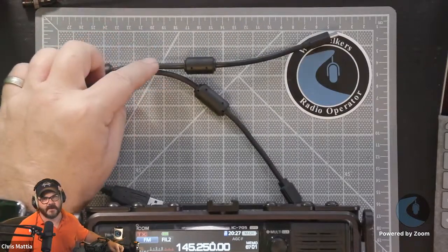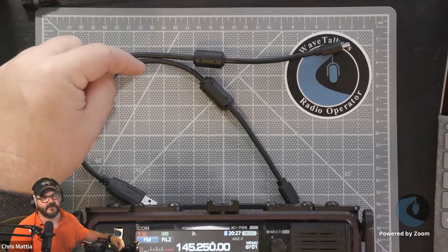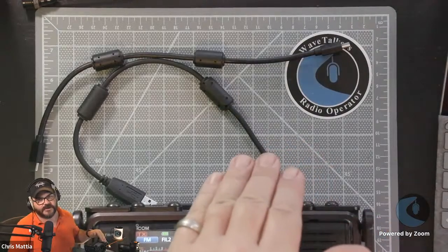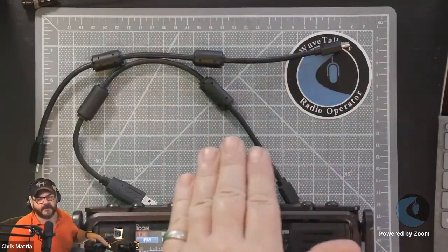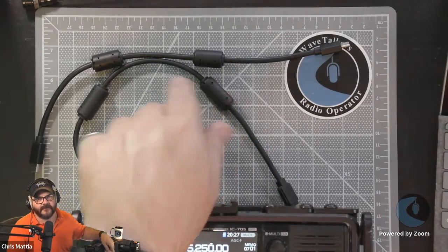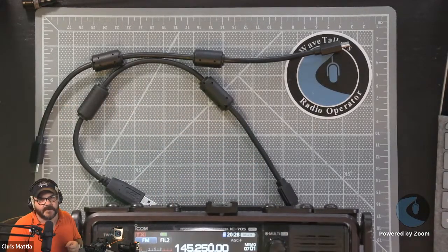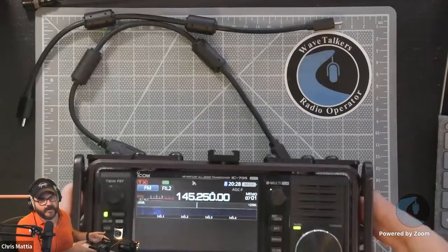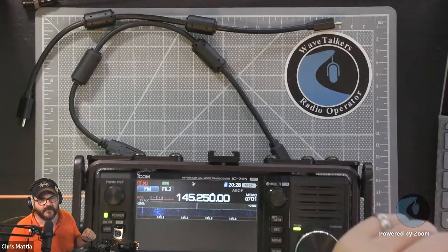I think they also have a USB micro cable, which is the one that the original port on the 705 is. The most common problem that I've found with doing digital and not getting traffic to go out has been that USB cable. Not all cables are created equal. You want a short cable, as short as you can get it, and you definitely want them loaded up with ferrites. The USB-A to USB micro cable that I used until I upgraded the board in this thing has 3 ferrites on one end, 2 ferrites on the other end of it.